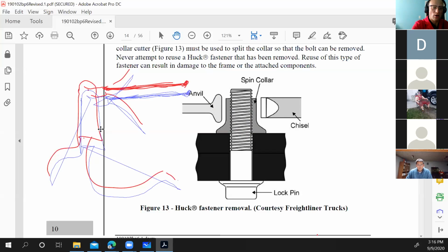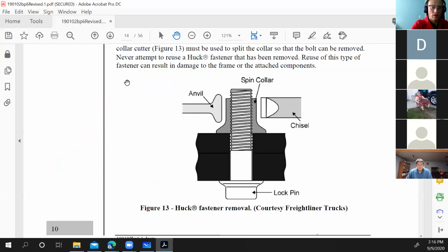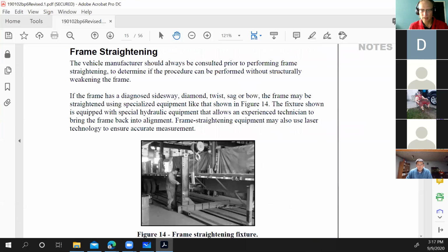It's really, really loud because of the air going through it, and they work great because anywhere you touch it, it will erase the steel and burn it away. Yet again, you have to be very skilled to use it too. It's very easy to gouge out sections of the frame with that. What was that called again? It's called an air arc.